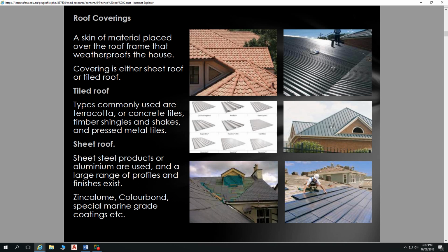Moving across to our custom orb sheeting, that, excluding the ceiling, gives us about 10 kilograms per square metre of weight. Significant differences in weight between those two roof coverings. Those loads have to be transferred through the roof framing and through the wall framing and then into the floor structure.